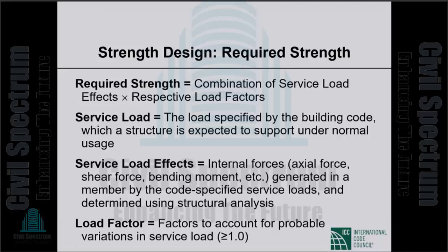Load factors are one or larger typically, although there are exceptions these days. Anyway, so service loads, load effects, we amplify the load effects by load factors because service loads may be exceeded, and then the factored service load effects are combined.